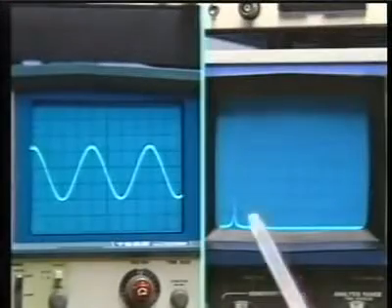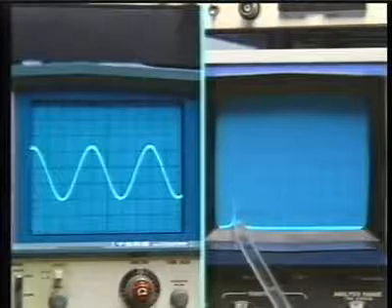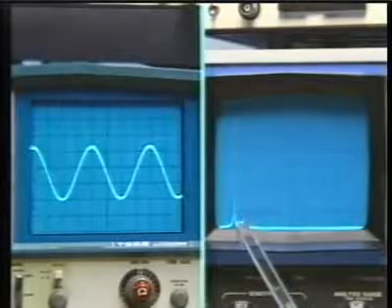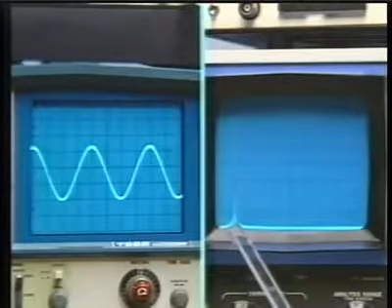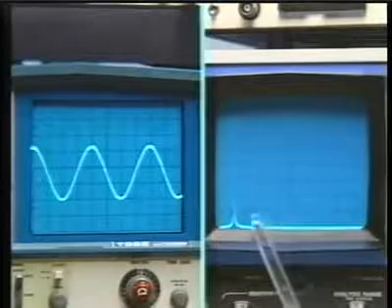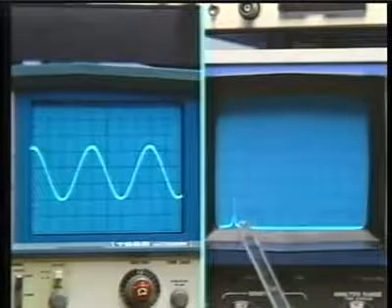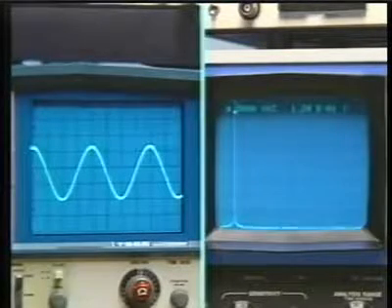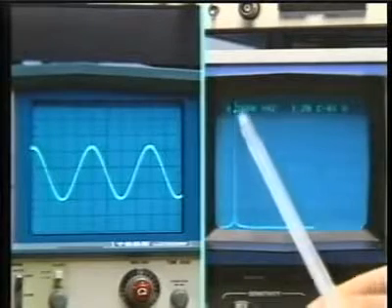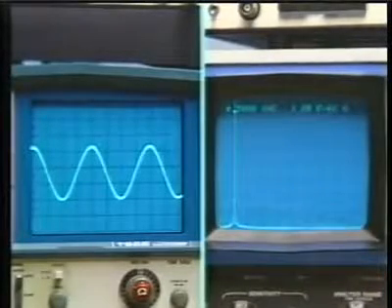We'll look at the square wave through the spectrum analyzer shortly, but first what we have is what we saw before, which is the sine wave. And just to point out again the fact that the sine wave spectrum, of course, is just a single line corresponding to the fundamental frequency. And here we have a frequency scale now that goes from 0 to 5 kilohertz. And this is then the 500 cycle sine wave. And in fact, we can flip the cursor on, and I happen to just magically have it positioned correctly, and we see that it's a 500 cycle sine wave.